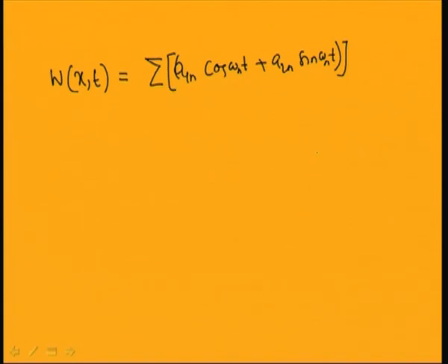For the simply supported beam, the mode shape reduces to the form sin n pi x by L. So, this is the transverse vibration for a simply supported beam. The total free vibration is expressed as the summation of all modal vibrations. If a particular mode is dominant, the resulting vibration will be that of that particular mode; otherwise it will be the summation of all the modes.